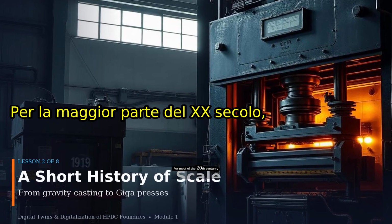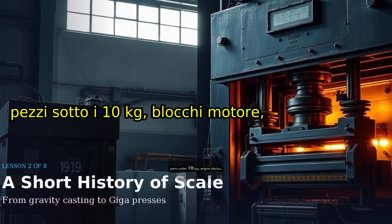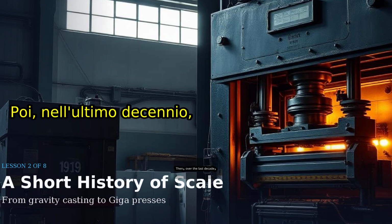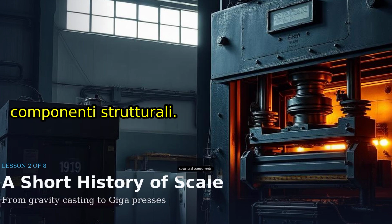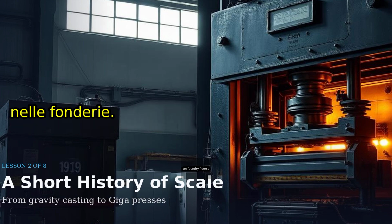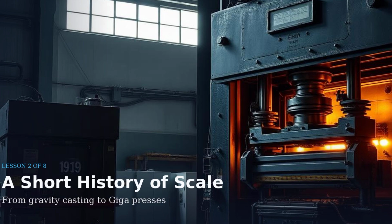For most of the 20th century, high-pressure die casting served the automotive industry with parts under 10 kilograms: engine blocks, gearbox housings, brackets. Locking forces of 800 to 1,600 tons were the norm. Then, over the last decade, electric vehicle architectures pushed the industry to consolidate structural components. Machines with 6,000, 9,000, and now over 16,000 tons of clamping force appeared on foundry floors. What used to be a component-scale process became a body-in-white scale process, almost overnight.